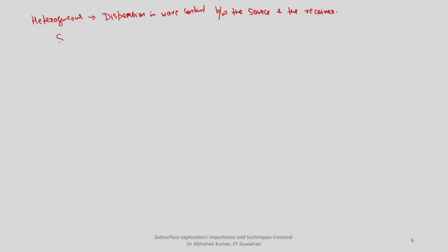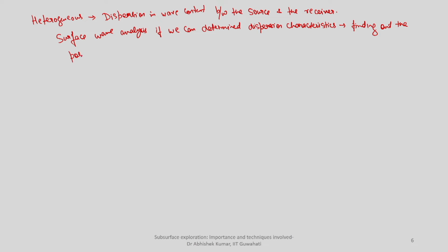So, in surface wave analysis, if we can determine the dispersion characteristics of the medium, this will lead to finding out the possible stratifications which are leading to the above heterogeneity or above dispersion.